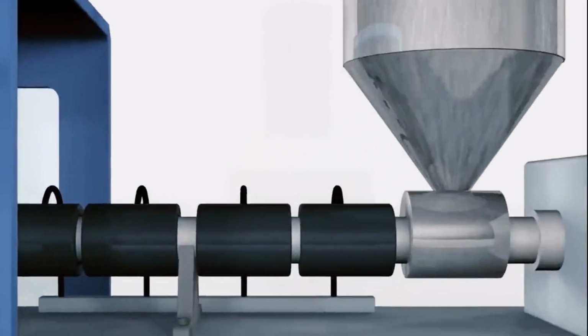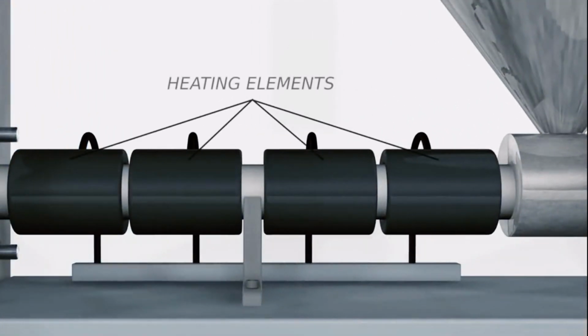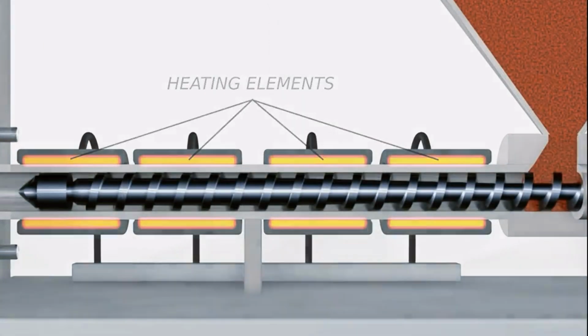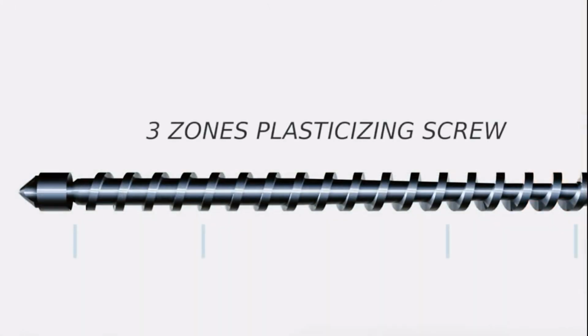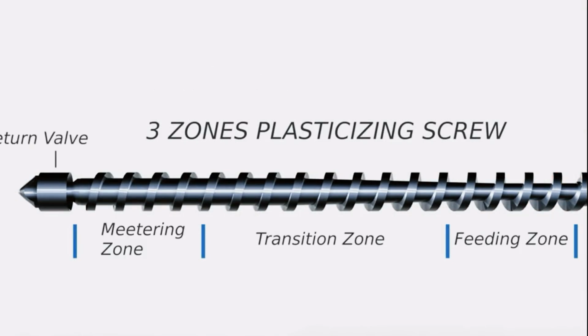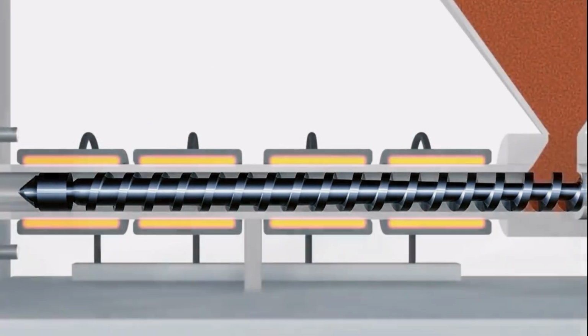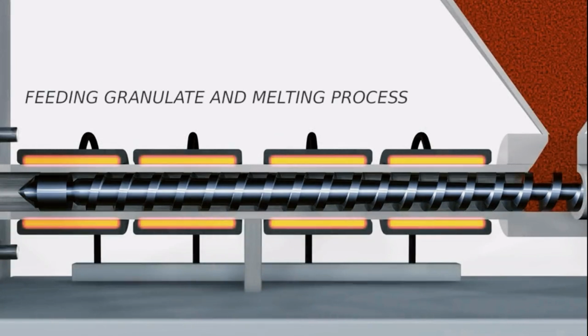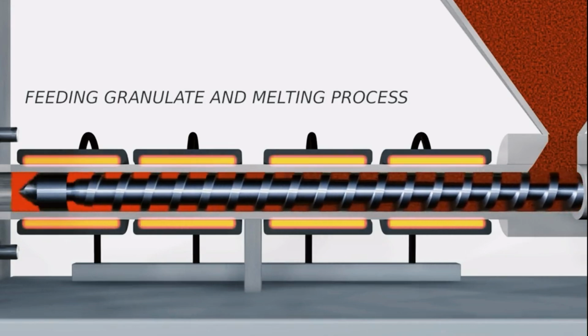In plastic injection filling, the plastic raw material is heated and melted in the barrel by the rotation of the screw. During the rotation of the screw, the raw material is transported forward on the one hand. On the other hand, the plastic is heated uniformly by shear action. When the plastic reaches a suitable molten state, the screw stops rotating and begins to push forward, injecting the plastic melt into the mold cavity through a nozzle.